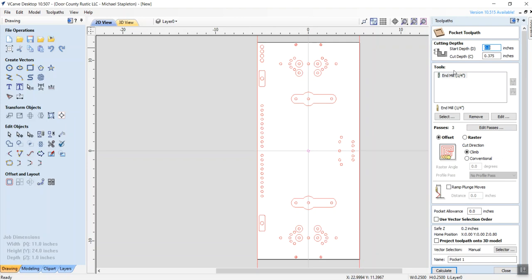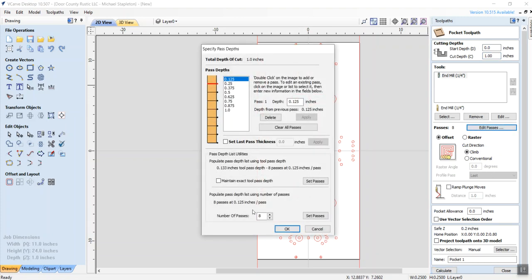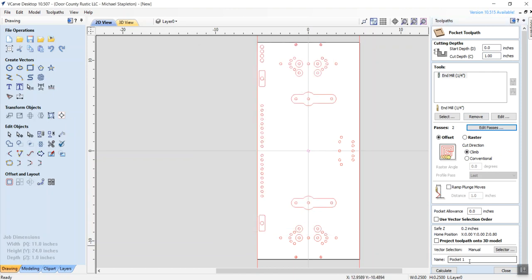That way, if I start a project, a CNC run, and something goes wrong, and I got to pull the board out or start all over again partway, halfway through, or whatever, do some fixes, well, now I always have that center pin of this particular set, and I'm all good to go. So I'm going to have 1.0 on that, 1.00. And since it's a 1/4 inch diameter, I can change my number of passes down to 2. That's plenty because it's just going straight down.